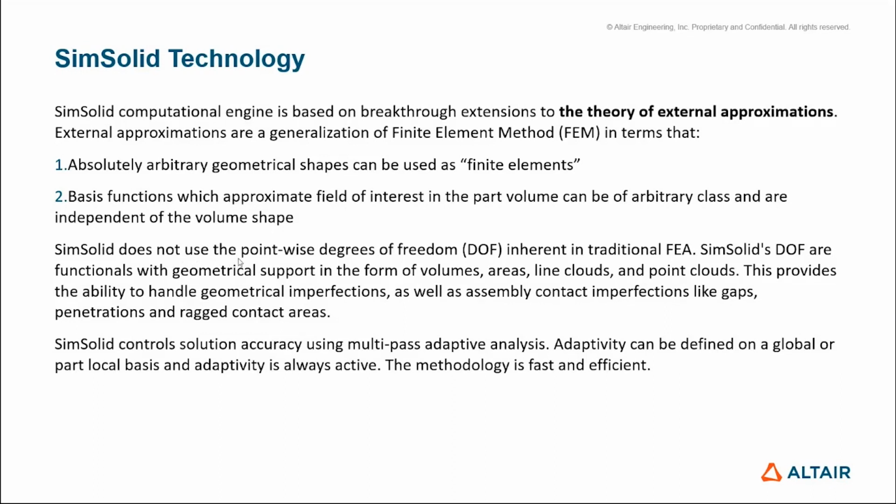So SimSolid does not use the point-wise degrees of freedom inherent in traditional FEA. In other words, it does not define nodes. SimSolid DOFs are degrees of freedom functionals with geometry support in the form of volumes and clouds. This provides the ability to handle geometric imperfections as well as assembly contact imperfections.